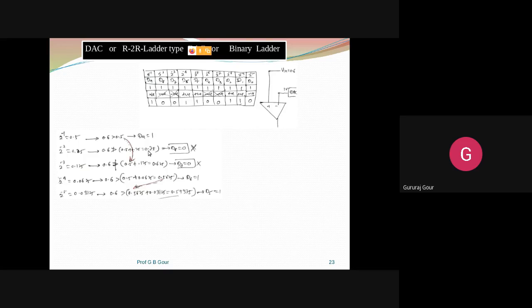This you underline, the sentence: we have to cumulatively go on adding that weight where the last bit was set. This is very important. So that's why we are adding here. You can see 0.5 is the weight where the last bit, the D9 bit, was set. We have to cumulatively add here with the present weight, that is 0.25.